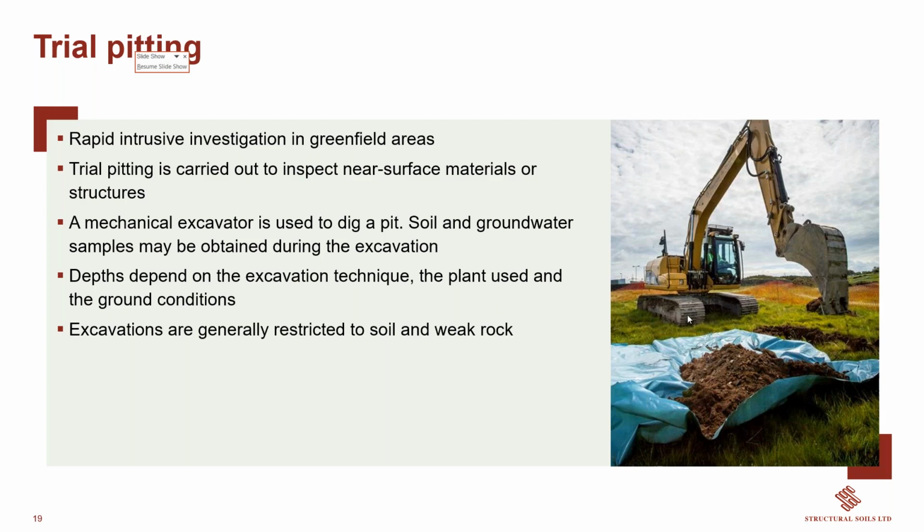If it's a big site and lots of trowel pits, the mobilization cost of getting a 360 excavator to the site is negligible. However, if you've just got 1 day on site, then a JCB 3CX that can travel on the road by itself is obviously a better tool.